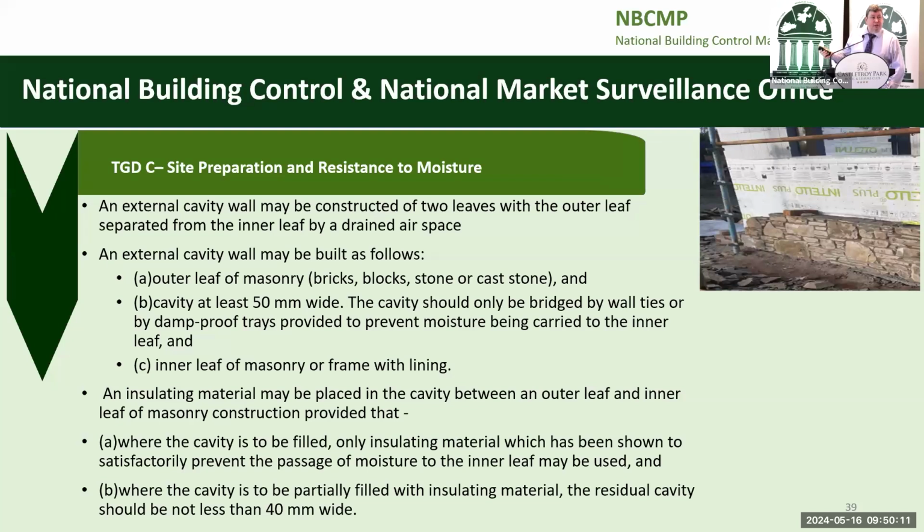I came across this one here, I thought it was really good. Intello membrane, used as a barrier for ICF on a house. Really, I don't think Intello membrane is to be used outside the building envelope. But they were building stone facing onto ICF. They didn't render the ICF, so they didn't comply with the Agrément Cert process. Now they're depending on this membrane, which is not designed for that purpose, not fit for that purpose, to act as a barrier.